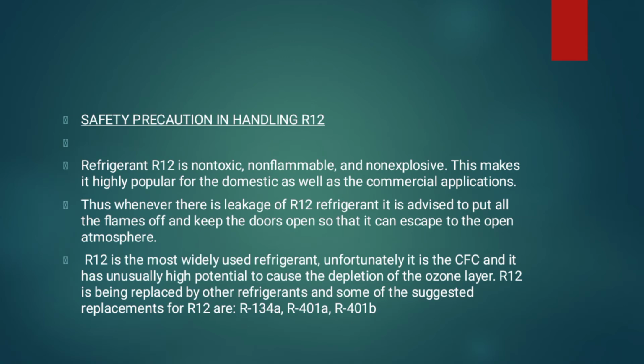So R12 is not actually used now, since it has a high potential of destroying our ozone layer. So there are some alternatives that we can use as refrigerants. The most common substitute for that one is the R134A. On modern cars, R134A is the refrigerant. This refrigerant is used widely on a variety of cars like Mercedes, Honda, and Toyota.